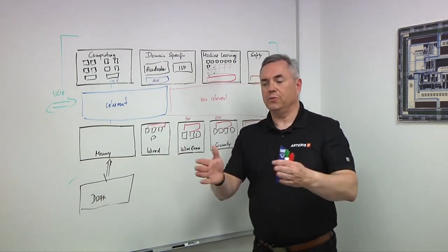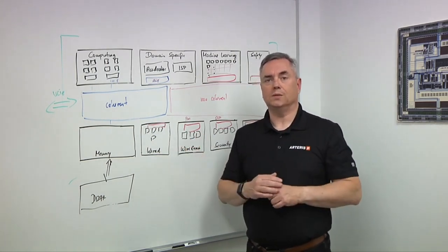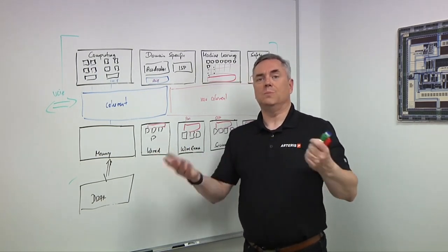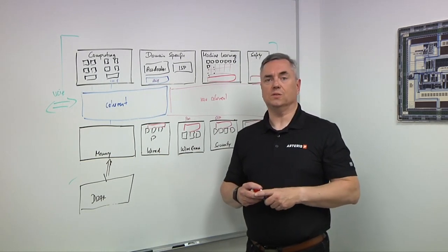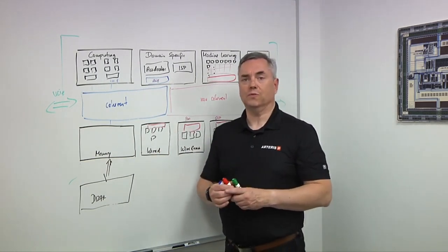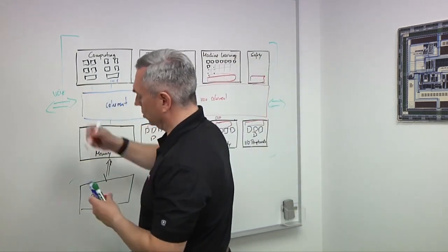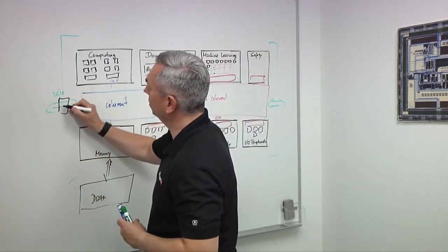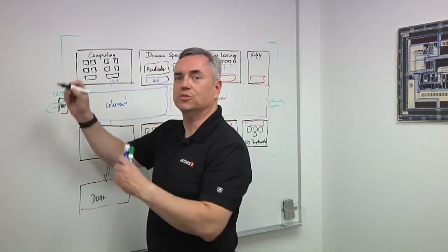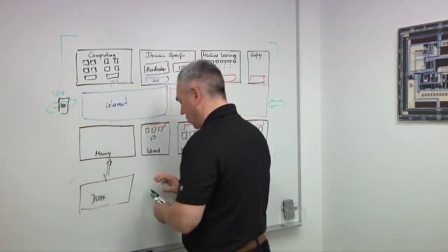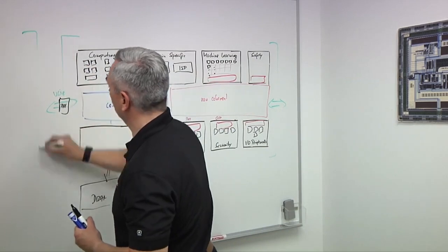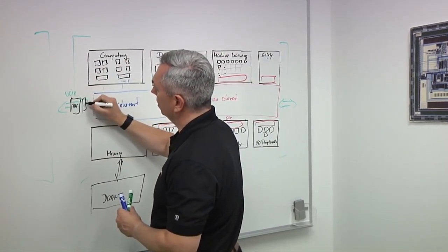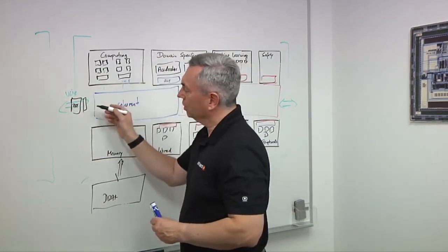There are really three levels of chiplet connections, right? So they're actually out there for quite some time. If you look at the big players like the AMDs, the NVIDIAs, the Intel, they control all of that, right? So they say, we just need our PHY here, just of course in air quotes, for the eye diagrams to work on the other side of my design as I connect things, and they can decide the protocol that goes in here. These things are called flits for the streaming. Those are the serialized protocols.